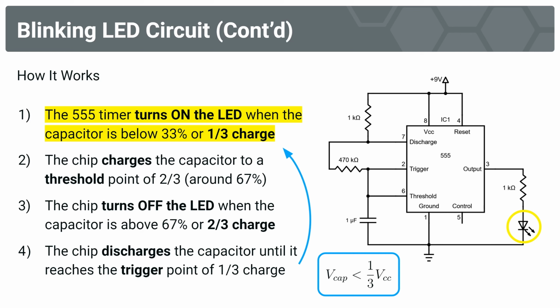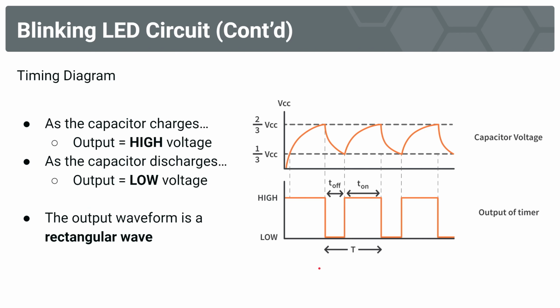The frequency of that process is determined by the amount of time it takes this capacitor to charge and discharge. So hopefully you can see how that concept of tau will start to tie back into our discussion of the 555 timer.